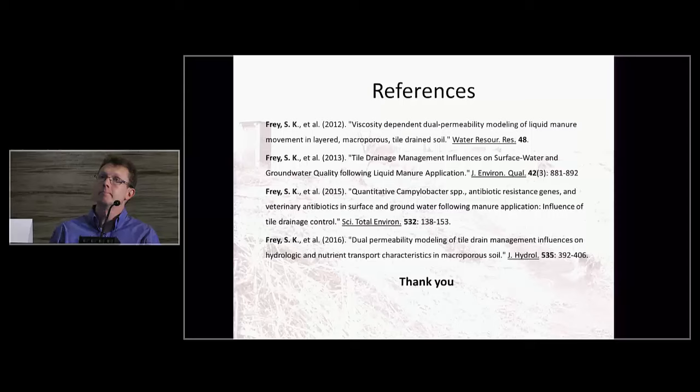Interesting to see, Steve, your results of controlled drainage, and especially I like the influence of upwelling groundwater on diluting the concentration in free drainage. Now, on the controlled drainage, you talk about that it holds the water back, so it cuts down some drainage volume, and you made a comment that it would migrate the nitrate to the groundwater. When I worked in Iowa, I was told that that migration of nitrate to the groundwater helps it to denitrify in the pathway in the drainage somewhere down the system. Any thoughts on that in your situation?